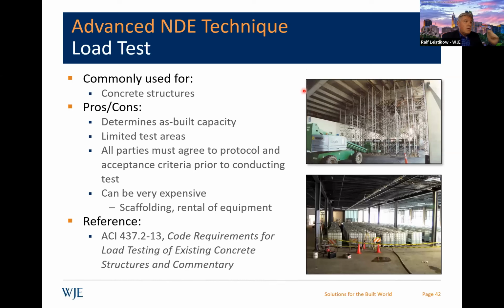This is actually load testing. Obviously it can be very destructive, but as you can see here, you try to prevent that by putting up scaffolding and things like that. On the top right corner is a project I was involved in at Lowe's Motor Speedway up in Charlotte. We tested a raker beam and put about 430,000 pounds of force in it. We designed this system here.